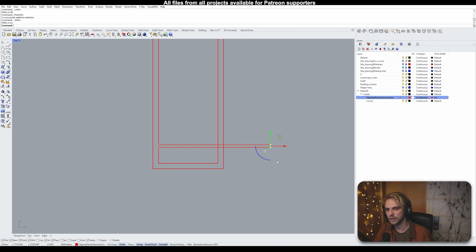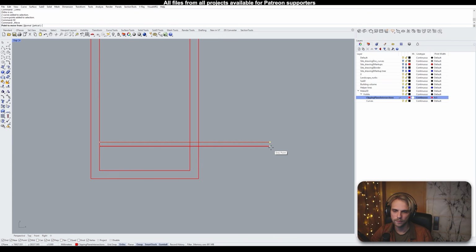F10 to get the control points of the 2 curves, and just move the curves, M, enter, back to the perspective snap. The snaps can all be controlled through here, and notice that I'm using end snap, near snap, point snap, midpoint snap, intersection, and perspective.